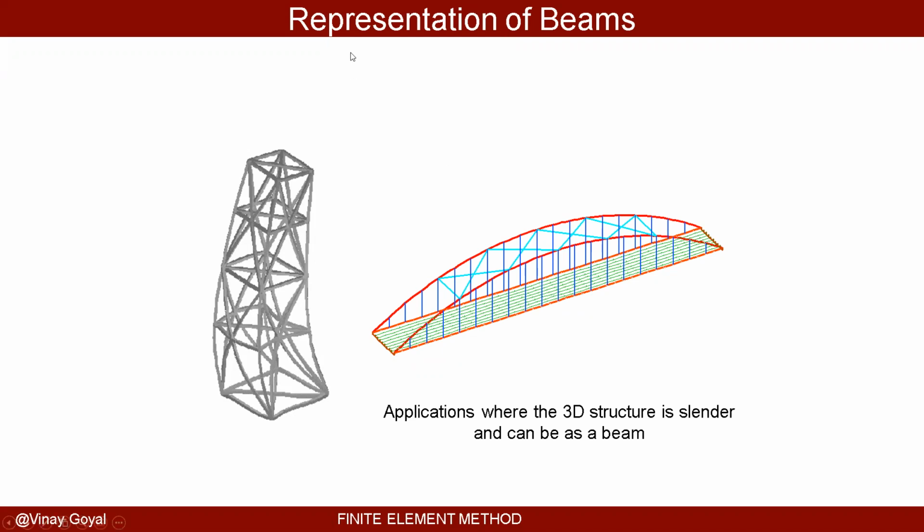Now, what you see here is a tower, like an electrical tower, that's supported by beams. You can see here there's cross members and support beams that are forming this particular structural civil engineering structure. And the point I want to make here is that we could model these things as 3D elements. Of course, this has a finite cross section, and I could potentially represent this as 3D elements, but that'll be computationally expensive, and it's not really required for this problem.